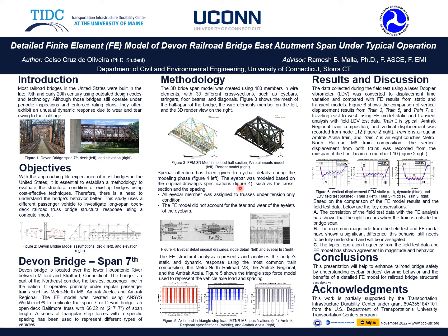And we give special attention to the I-bar details because from the research and what we found in the field, the I-bars are not evenly loaded. For example, the bottom I-bars right here in the middle, the bottom chord, it's 10 I-bars and they're all bundled together, but they are not uniformly loaded. Although in the design you assume that they're all taking the same stress, in reality, some of them take more stress than the others. And we want to capture that information. So that's why we decided to give more detail to the I-bars.